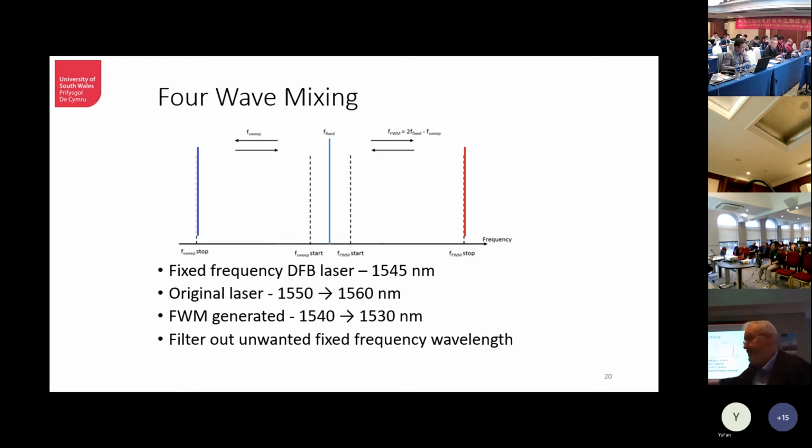So what we did purposely towards the end of the 90s, people recognized this and said, wait a minute, don't make it 0 dispersion. We put a little dispersion in there, so we kill off this crosstalk. So we killed it off. We got rid of 4-wave mixing because of the equal channel spacing.